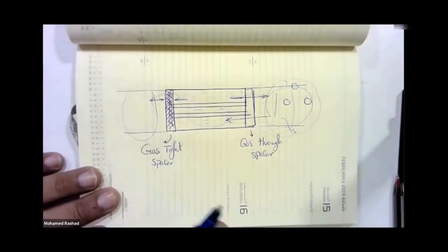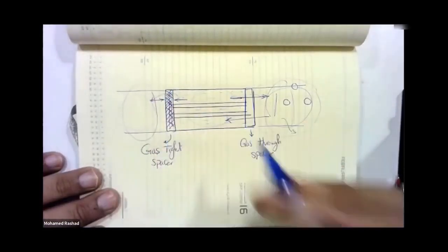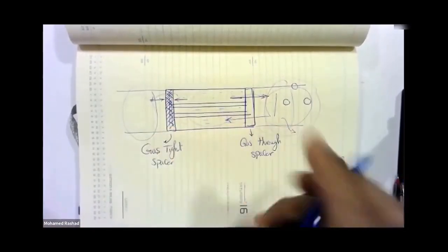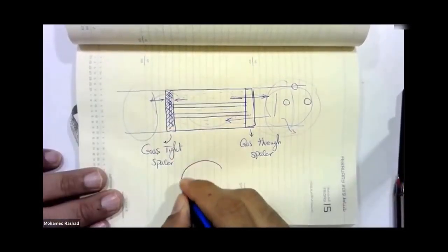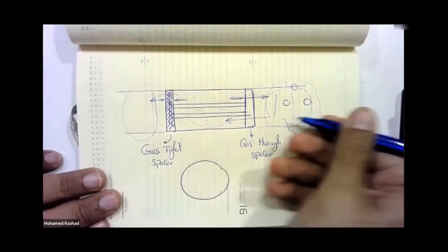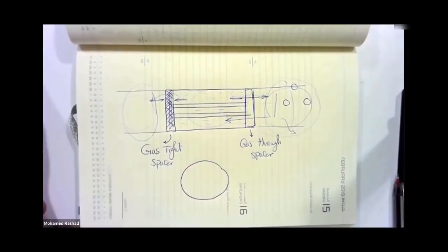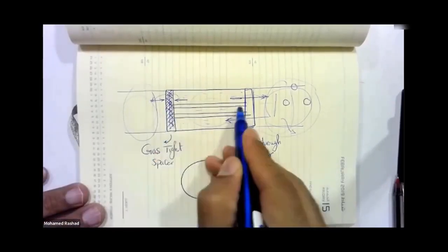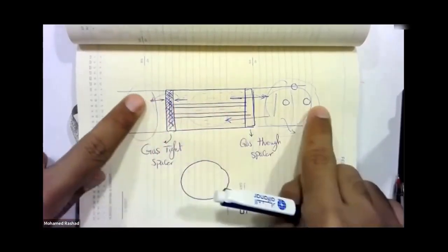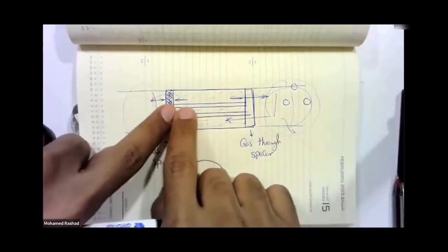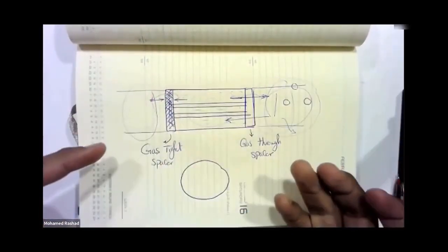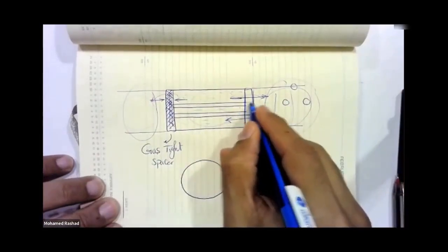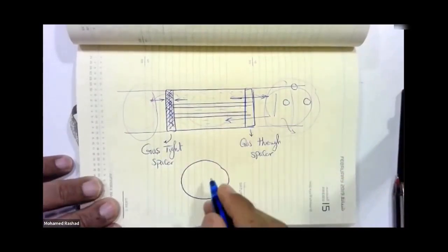Excellent. Great. So now what's the purpose of this spacer? Generally, the presence of a spacer, whether it's gas-tight or gas-through, the idea, if you look at it from the side in a circular shape like we saw in the video, is that the bus bar running through shouldn't be extended 10, 20, 30, 40 meters, all stretched out without supports. So between this compartment and that compartment, it needs to rest on something with support.